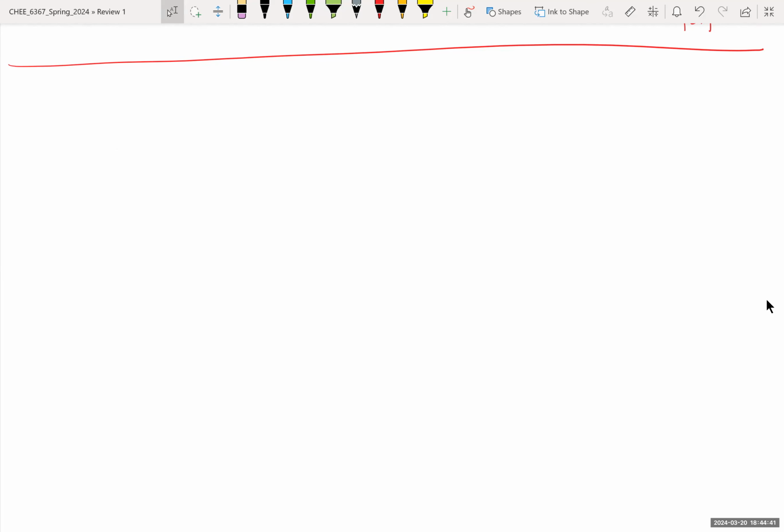But it needs to know something about the process, not just any process. A critical element about the process is the sign of the steady state gain. If you make a step change in the manipulated input, the output eventually goes here. In fact, difficult processes are processes with inverse response, not this, but this inverse response.